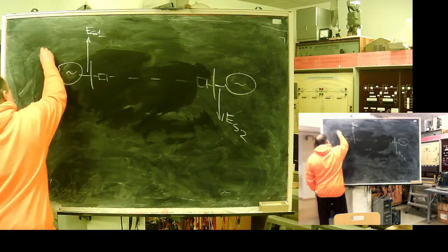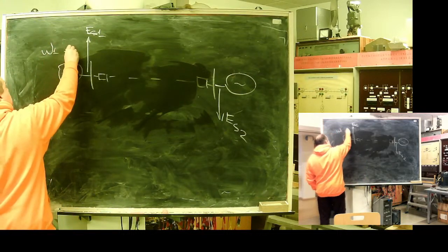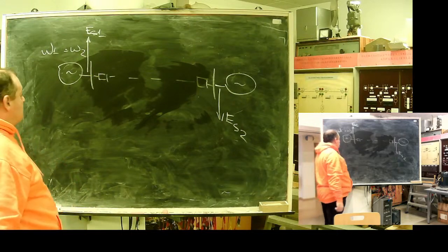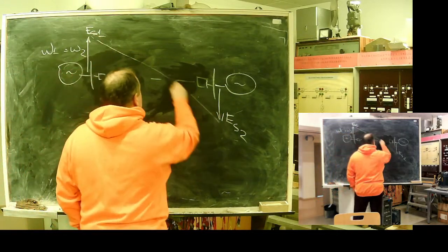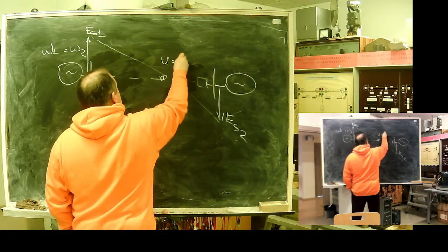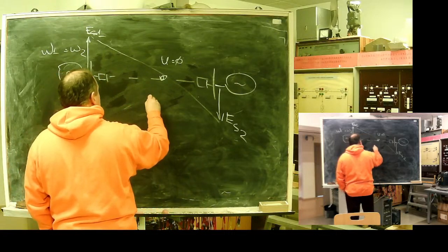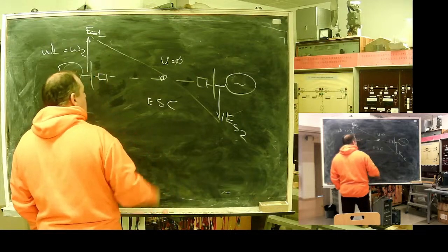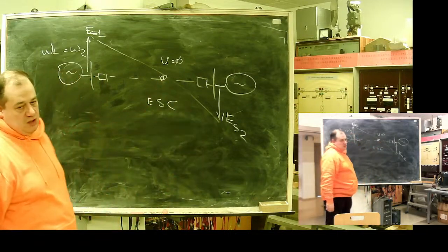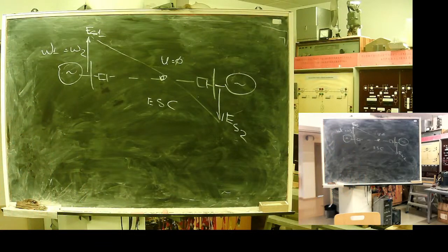The frequency on one side is not equal to the frequency on the second side. It's possible. Here, the point where the voltage is zero is the center of swing, the electrical swing center. At this point, for distance protection, it is a three-phase fault. It will be inside an operation zone, and we will get a false trip, false line disconnection, making the problem more severe.